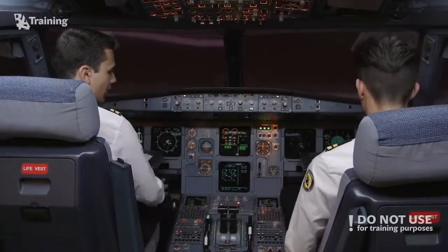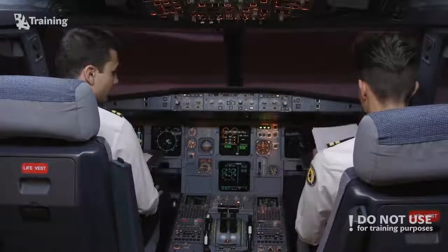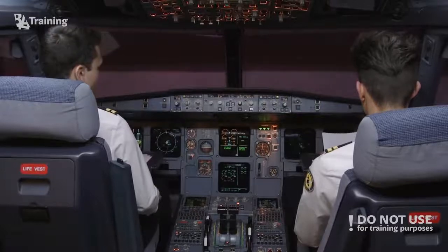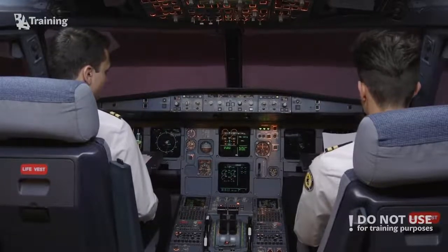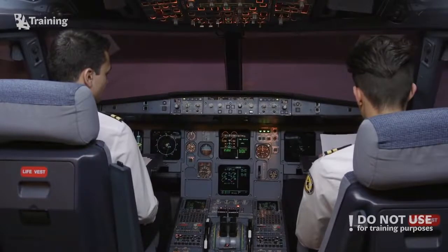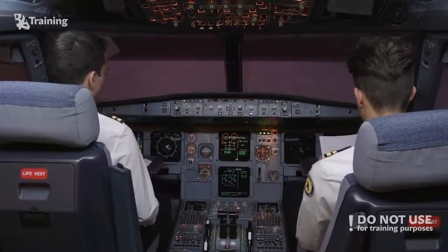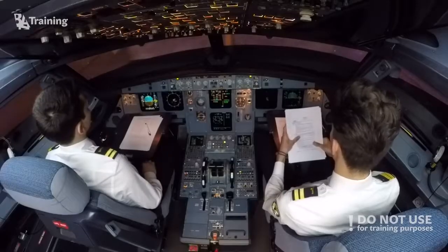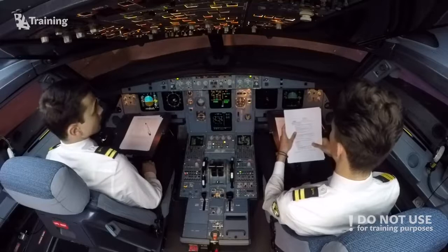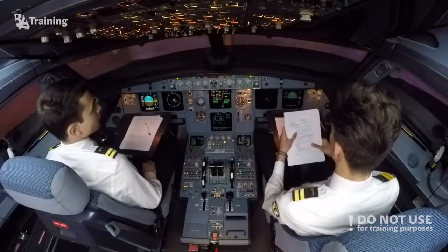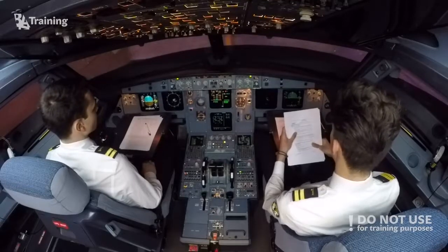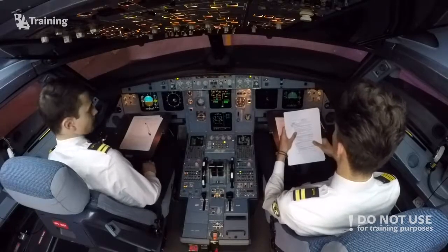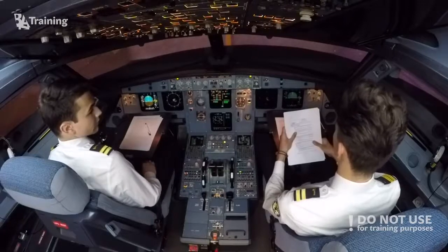Okay, let's go with the manual engine start procedure. Okay, manual engine start procedure. Note: during a manual engine start, if the flight crew suspects an engine start malfunction or if an engine-related ECAM alert is triggered, the pilot flying must abort the start sequence as follows. Before the pilot flying sets the engine master lever to on, the pilot flying must set the engine manual start pushbutton switch to off. After the pilot flying sets the engine master lever to on, the pilot flying must set the engine master lever to off and then set the engine manual start pushbutton switch to off.